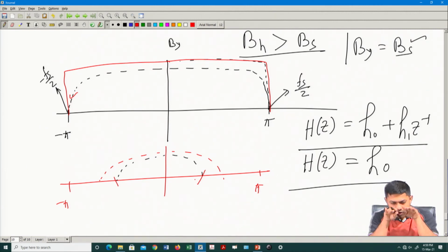I will see that across my transmission window, the channel has presence of frequencies. So, the channel does not give any distortion or does not cut off anything as long as I am within my transmission bandwidth. That means, if I just transmit 10 megahertz and I do not look at anything beyond that, because that is my transmission bandwidth.